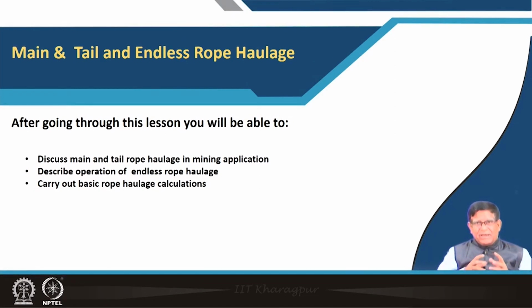At any time, if a simple spark comes out, there will be an explosion. That is why you may know that in any underground gassy coal mine you cannot use any motor or electrical appliance unless the enclosure is flame proof, and that flame proofness has to be tested and certified by the Director General of Mine Safety, with testing facilities at Dhanbad.